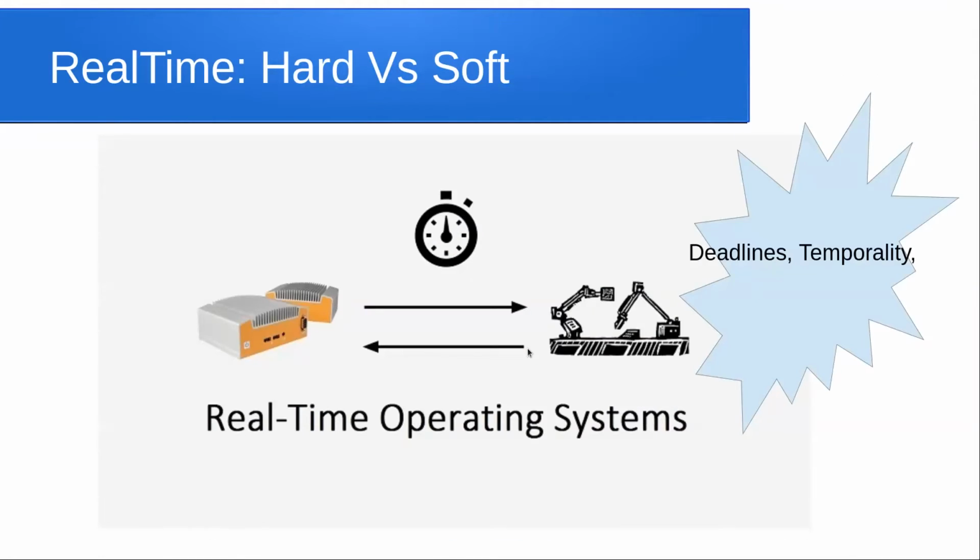right? So on the other hand, when we talk of realizing IoT systems that need to have real-time or hard real-time behavior, it is recommended that such an IoT system be implemented on top of a real-time operating system or a real-time kernel, because IoT application developers need to focus on their end application rather than on deadlines or temporality-related functionality to be realized in the software. We'll see that at the end, in much more detail, with a real-time kernel that we have developed at IIT.